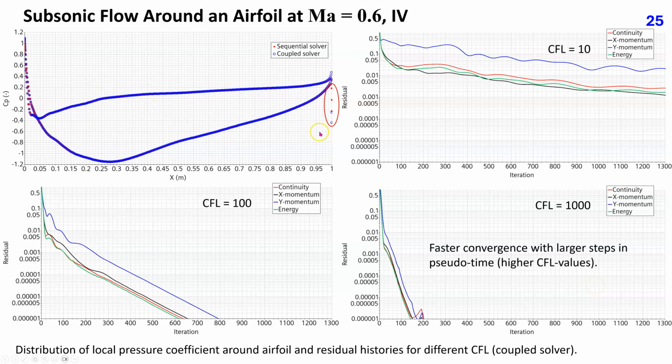This plot shows the variation of pressure coefficient along airfoil surface, computed with the two solver versions. The results from coupled solver and simple algorithm are not identical because the computation of mass fluxes is slightly different. The differences are very small except at the trailing edge. The marked points are related to disturbances seen in contour plots in the previous slide.